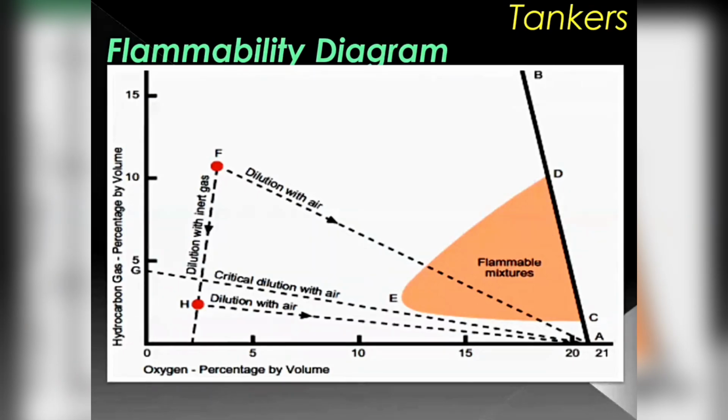But I was just saying that if the atmosphere is too lean, then we can continue like that. That's why I asked you. But to maintain it too lean, you have to continuously monitor it. You're taking a risk, and there is not much of a difference. The atmosphere might enter the flammable range, as small pockets or a few pockets in the tank may have a high percentage and fall into this range. Even if you are continuously venting the tank, there are still some pockets left untouched where the hydrocarbon percentage is very high. So it's just taking a risk, and it's absolutely not necessary to take a risk.